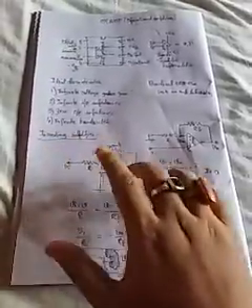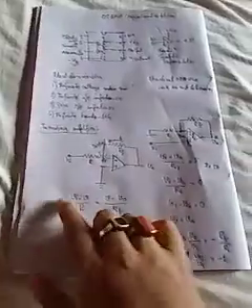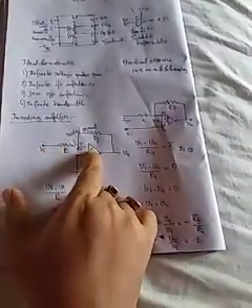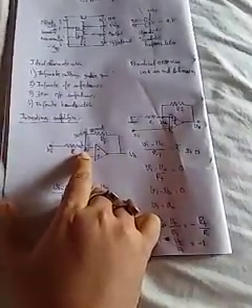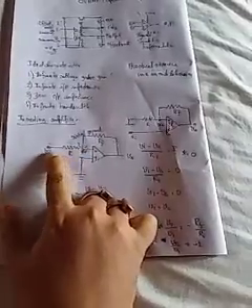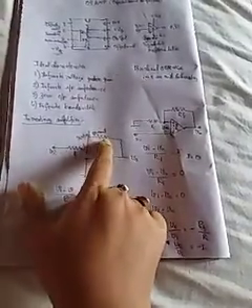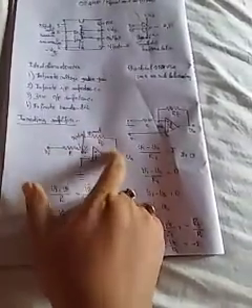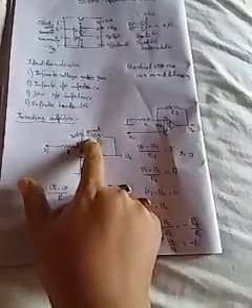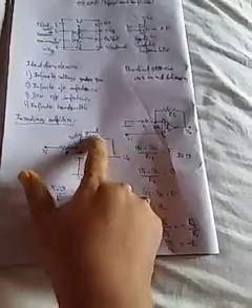Here this is the inverting amplifier, because I told you previously that an op-amp also performs as an inverting amplifier. Here the voltage Vi is applied at the input terminal, and this is the virtual ground. It is connected through the resistance R, and RF is the feedback resistance. It is called feedback because this is the common path between the input and the output terminal.